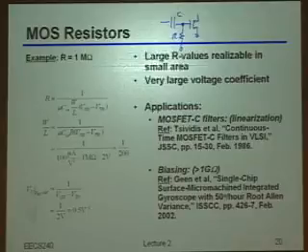Now, in many cases, you probably don't care, right? So as an example, if it was, let's make something up, 10 kilohertz instead of 100 kilohertz, as long as all of my signal stuff is way above that frequency anyways, I may not care all that much, right? What's the only other thing you actually care about in terms of the value of that resistor? So let's say, indeed, you don't care too much what the zero set by that is. What else might you care about in terms of that resistor?